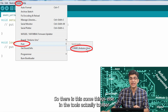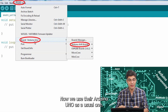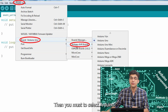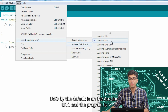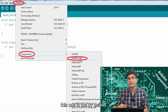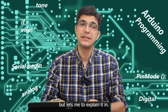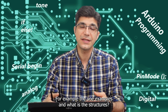So there is something else in the toolbar actually. From here you can choose the board. Now we use the Arduino Uno as the usual one. Then you must select Arduino Uno, but by default it is on Arduino Uno. And the programmer should also be AVRISP mkII. This one is the default. Other options I will explain, but let me explain them in, for example, one of the examples.